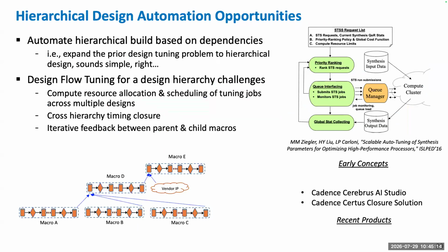I'll mention this briefly, but hierarchical design is another task. If I didn't mention it, I would have felt bad, because a key challenge is that we're doing this so far in the context of a single context or design macro. In practice, we have multiple levels of hierarchy, many macros in a complex chip design, and we really have to come up with a strategy to handle them all. I'll leave it at that for brevity, but the key takeaway is that we can think about the macros in their own context, but we will eventually have to roll this up through the hierarchy.